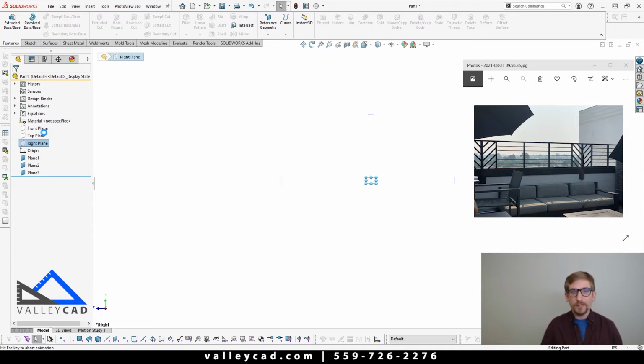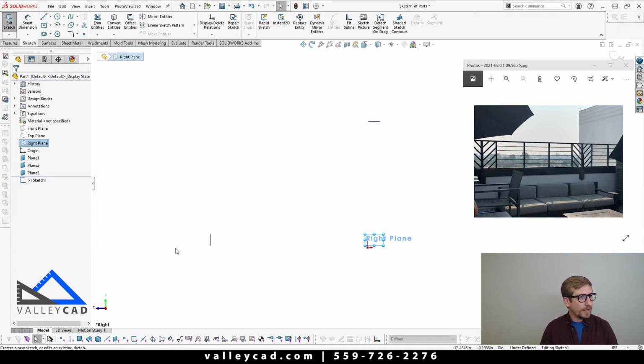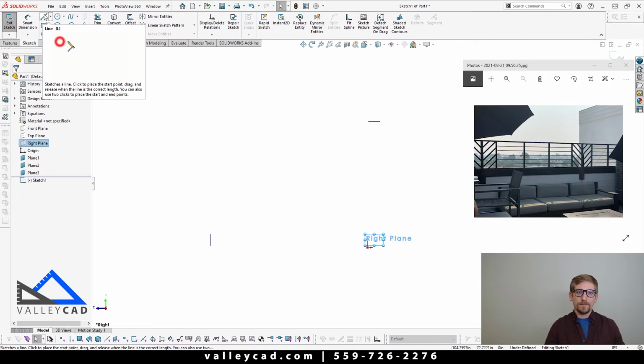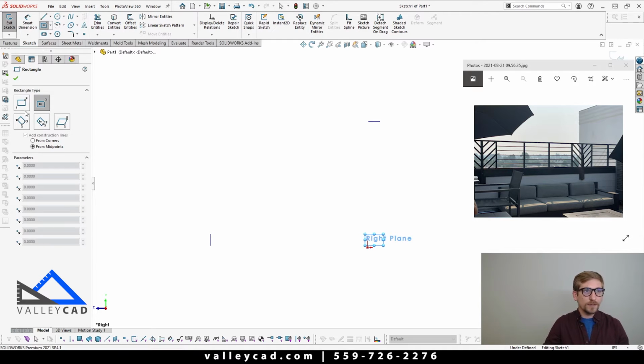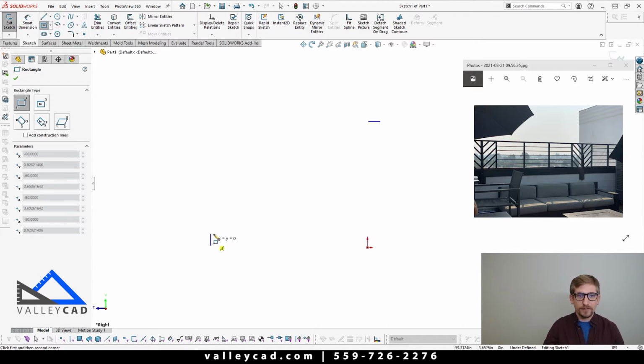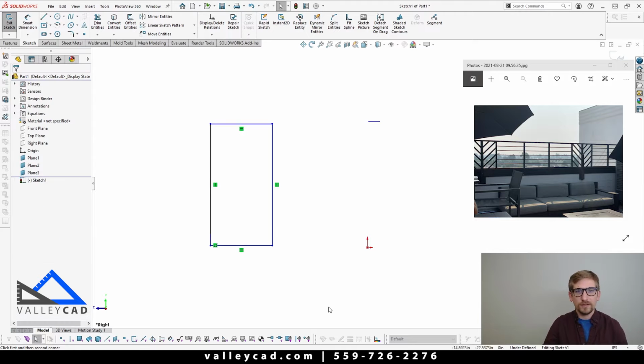So coming in here, creating a new sketch, we'll set it up to where we're gonna work on that little chevron shape first. I'm gonna be looking at it on the left side of my part here. So what I'm gonna do is simply come in and create a rectangle like so, and have that rectangle come up, and we'll make it so it's the height of there, and we'll simply say good to that.